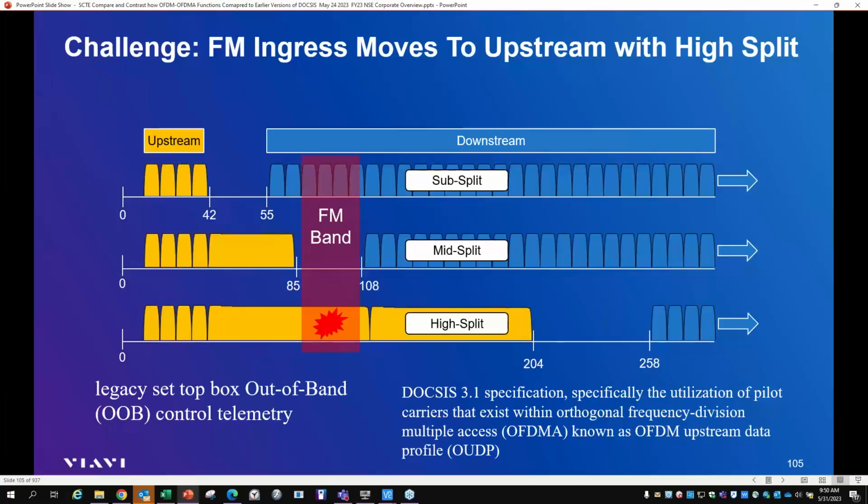So you may fix one and say, well, it did make a difference. Well, it probably did make a difference, but because it's there in other places, it might go down just a little bit because of power addition, but you'll still see that carrier. So it'll be another peel the onion exercise where, okay, I fixed one, but that's just one. There's going to be more. So you may be going through that distribution leg a few times before you get all the sources of that FM ingress. Absolutely.